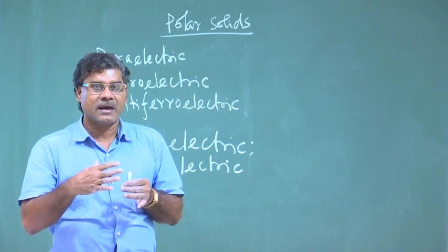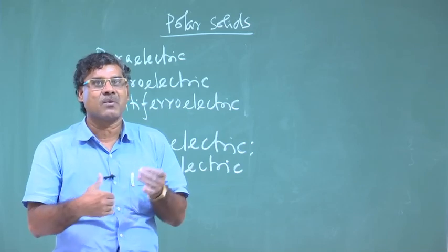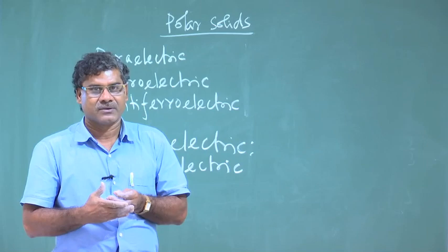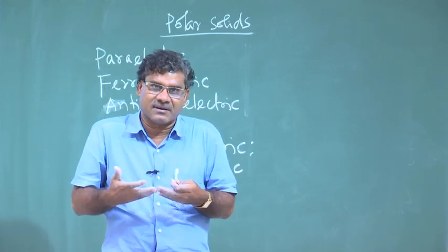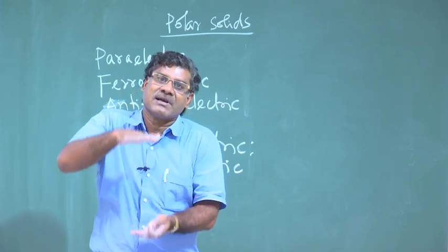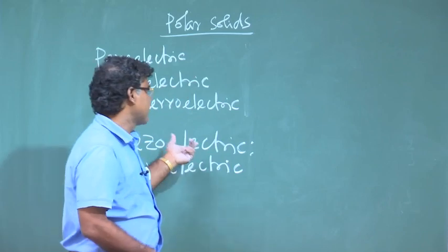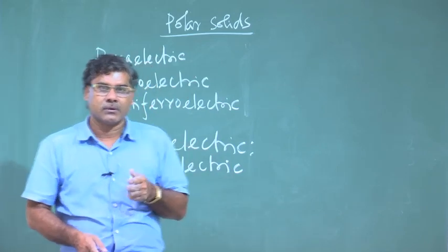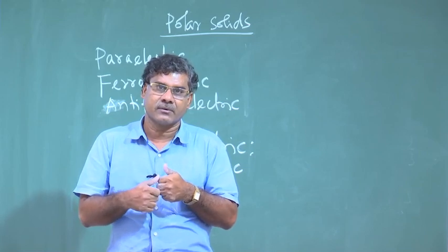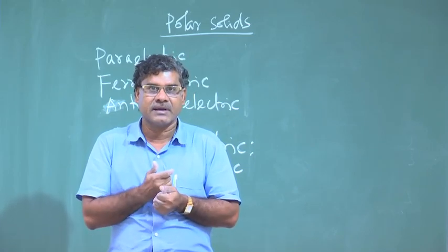So, pressure is giving voltage; now if you apply voltage, it will give pressure. Due to it, this material will feel stress, it feels force, and due to that it will change its dimension. So, that material is used to measure displacement in nanometer order.